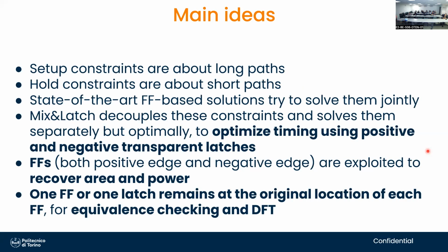So just in summary, in a circuit design, you are trying to make data fly through combinational logic from a launching memory element to a capturing memory element. The data can start running when the launching memory element opens, and it has to get to the destination by the time the capturing memory element closes. So you have, like in a race, a gate that opens, you run through a course, and then you have to get to your destination before the terminating gate closes. Otherwise, there is a miscomputation.